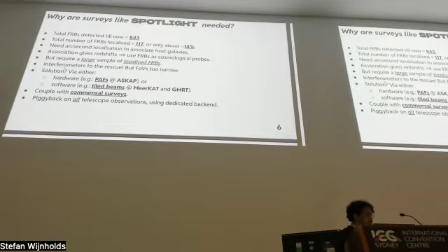So with Spotlight, we are going to form multiple beams in the field of view. That can be done using hardware such as phased array feeds, as in ASKAP, or in software with tied-array beams, as in MeerKAT. We are going to follow the software route, where in the digital backend we will form these multiple beams inside the field of view. Also, the GMRT is a time sharing system. It's not a dedicated telescope, so it's used for lots of other applications by different people all around the world. So to increase the possibility of detecting such FRBs, we will have a commensal search.